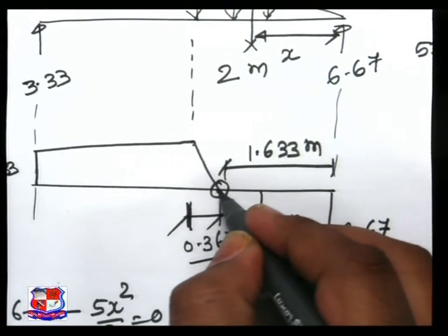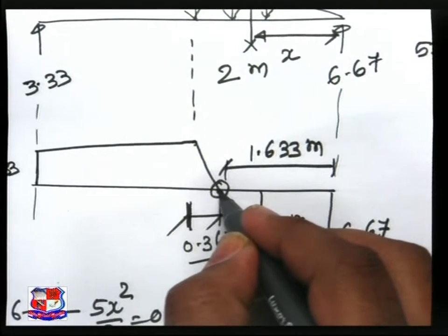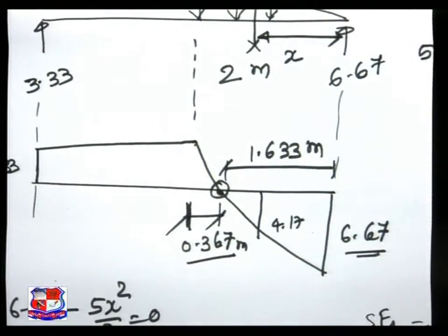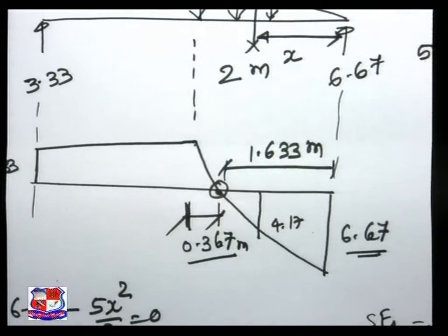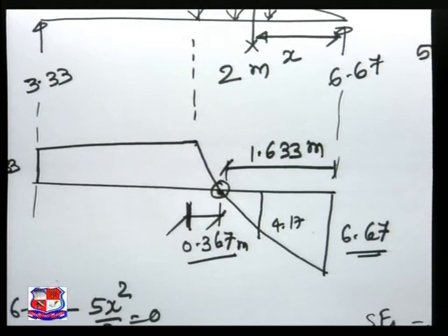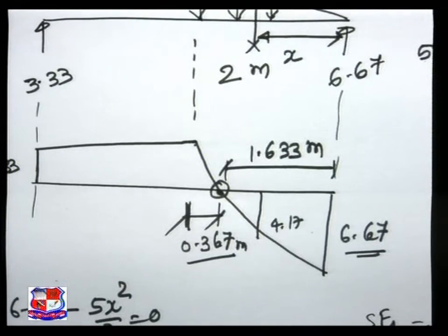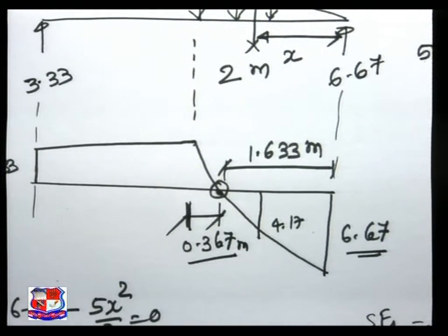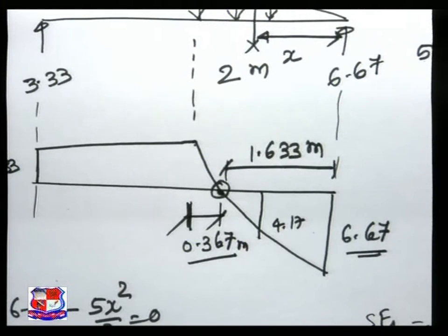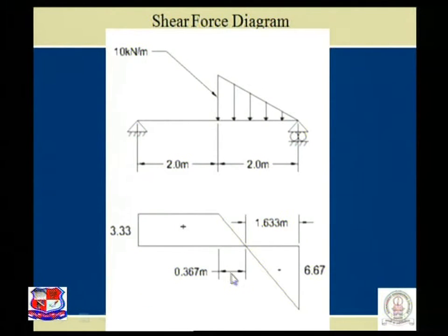The point at which the shear force is 0, we will obtain maximum bending moment. So visualize over here 0.367 on this slide, on the PPT, please visualize. Yes, 0.367, and be careful, the nature of the parabola is of this kind.